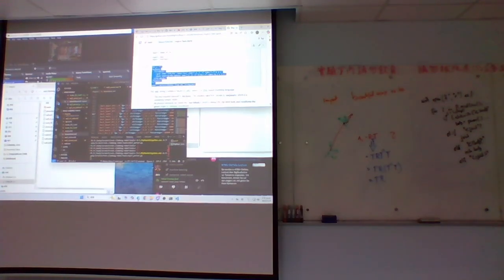So you want to change the starting position, and then move the joints to a reasonable position, and then you put the handhold there. That's easier than putting the handhold and then having to figure it out at the beginning. But yeah, good, nice. So you have your robot inside of MuJoCo.